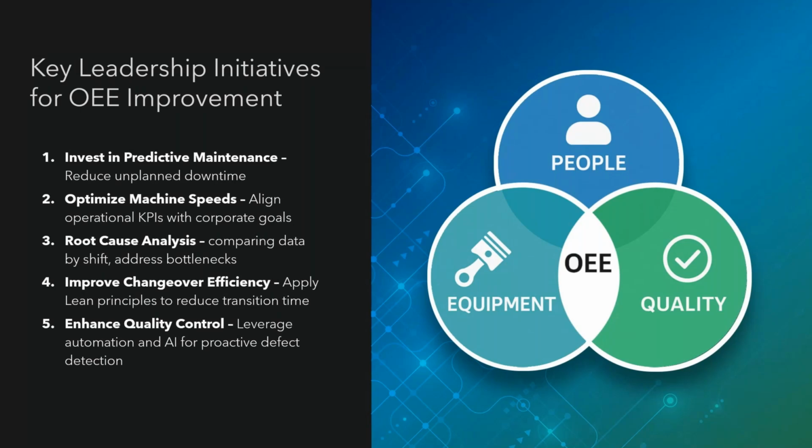Another aspect relating to performance, that people in operations care about, is machine speeds. Obviously, faster machine speed sounds great, but you also require balanced machine speeds across the line. So when we do OEE solutions, we really focus on understanding starved and blocked stations. If things are not running in a cohesive manner, you can get a buildup of parts that blocks certain stations, or we starve certain stations from not having input product.